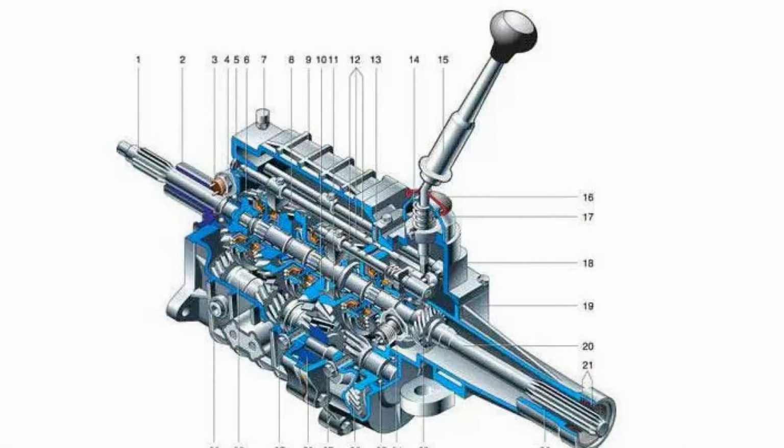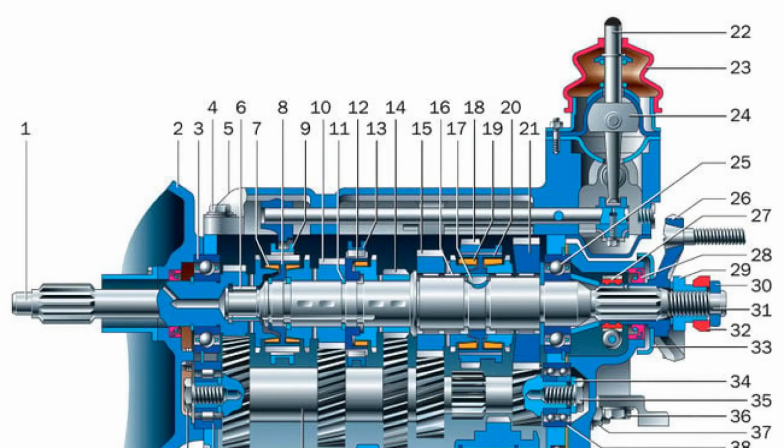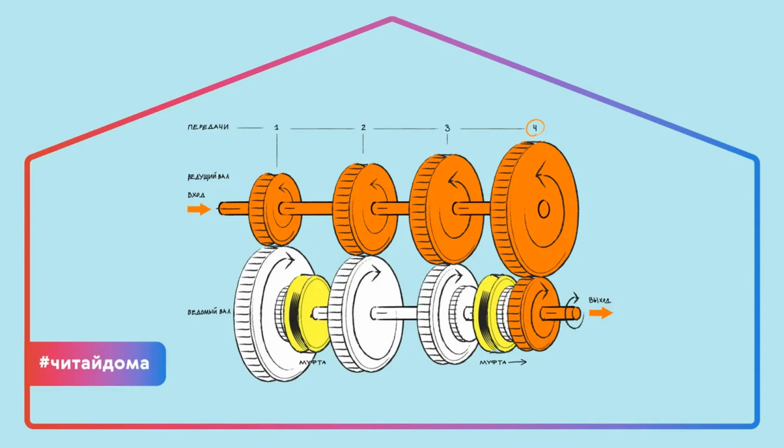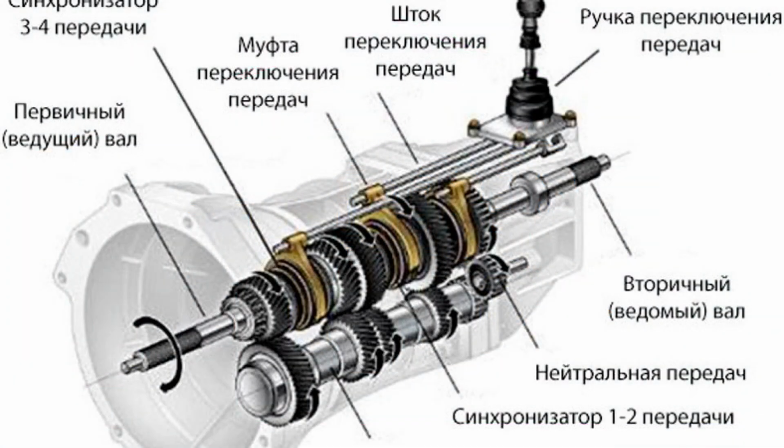And that's where the transmission comes in. The transmission is able to maintain both your engine speed and wheel speed at optimum speeds, and it sends power to the differentials that turn the wheels. It does this through the use of gear ratios, but how do gear ratios work? What are gear ratios? A transmission uses toothed gears that interact with each other to produce torque, and the gear ratio refers to the relationship of the gears to each other.